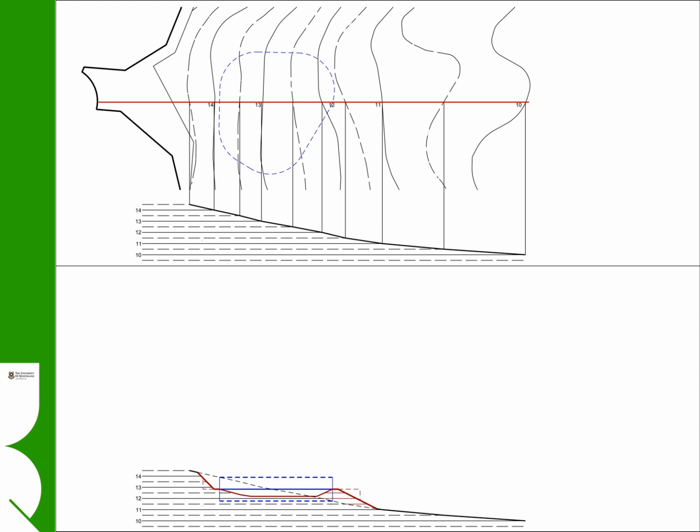platform for the pond. This is where the surface height of the pond is approximately halfway between the intersection of the highest part of the slope and the lowest part of the slope. Once the height is established, we then show the amount of cut and fill either side of the pond.